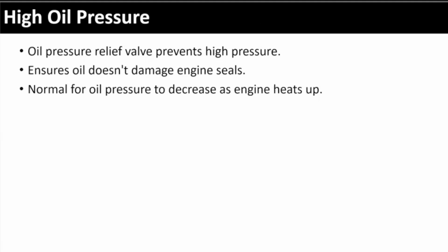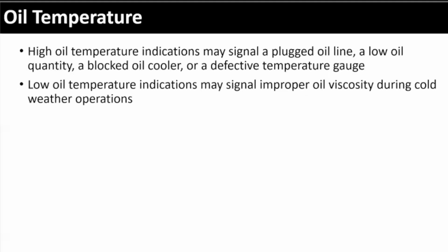Oil pressure, with high pressure, normally they have a relief, right? You're rarely going to see high oil pressure because the system is going to be built to avoid that. Make sure that we don't blow the seals, make sure that we don't have those other problems. Your pressure is going to increase as it heats up, that's okay, as long as it stays in that green zone. High oil temperature, again, there could be something defective in the system, it's not circulating correctly.